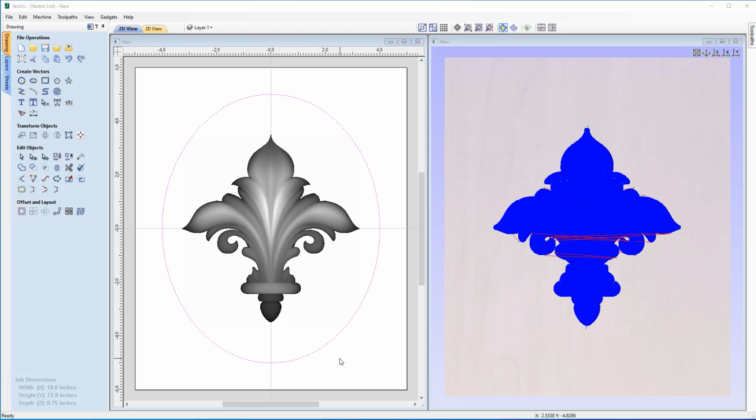Now we're going to use this new vector, this new ellipse that we've added, as a profile cut when we come to cut out our sign. And also we will use it to define the space between our toolpath that we created in Design Make Machinist and the border of our sign. So we can machine out the extra material that's in between them in this space here, in this white space just here.